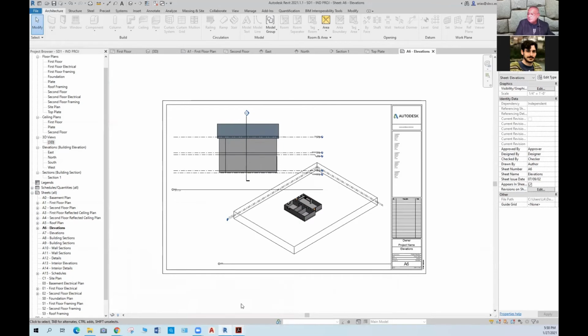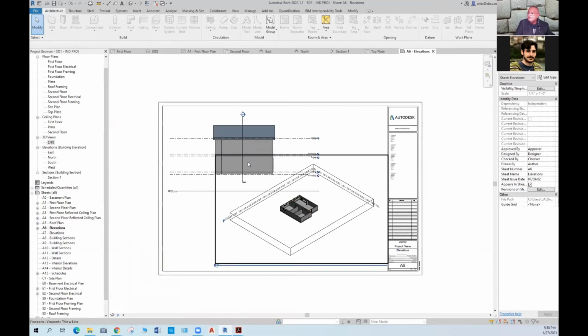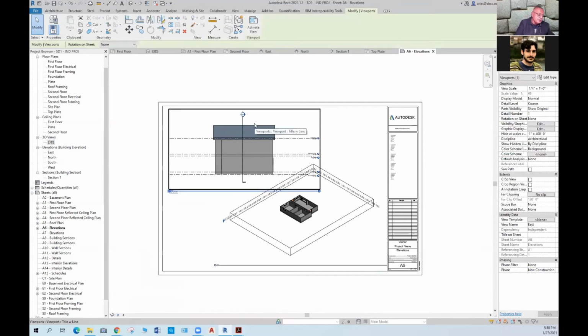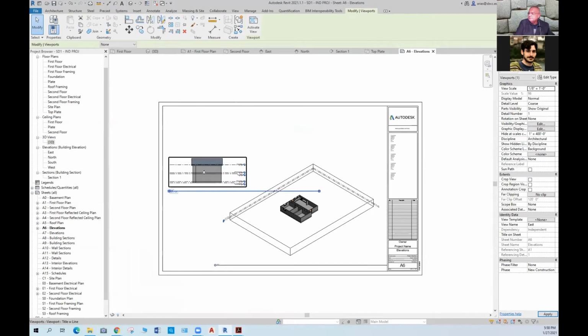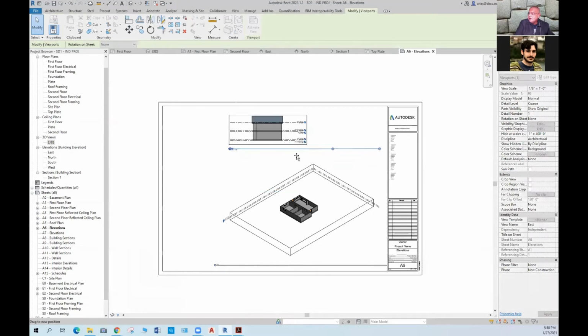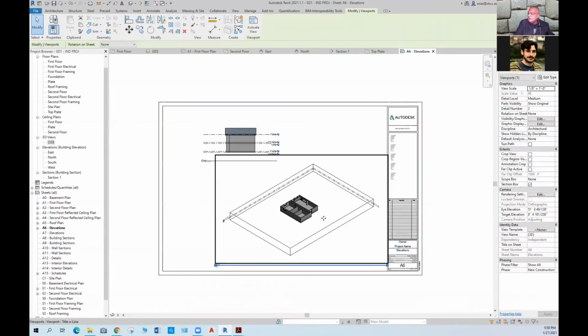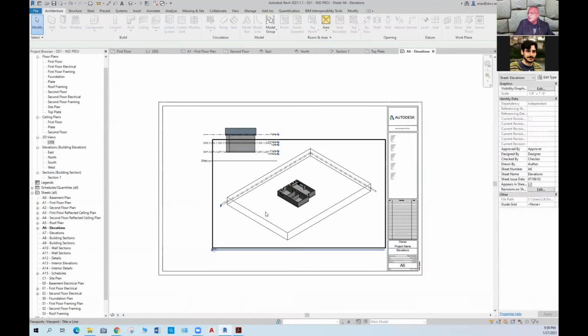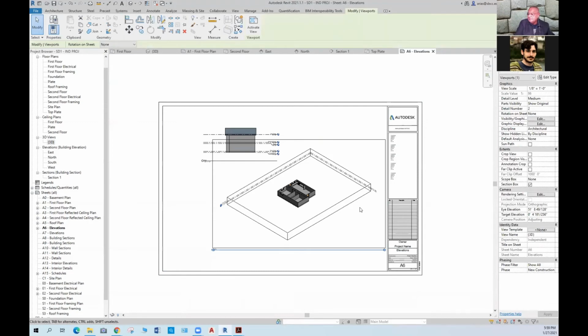Now, when you are ready to print, you can modify the scale of the views by clicking on each view. For example, we said that for schematic design, we should be printing at 1/8 max. So I select the view, and then I change the view scale right here in the properties. Right, and then I can drag that. And then I select that, and that one is already 1/8. So that's great. But if I wanted a different scale, I can select the view and change it here.